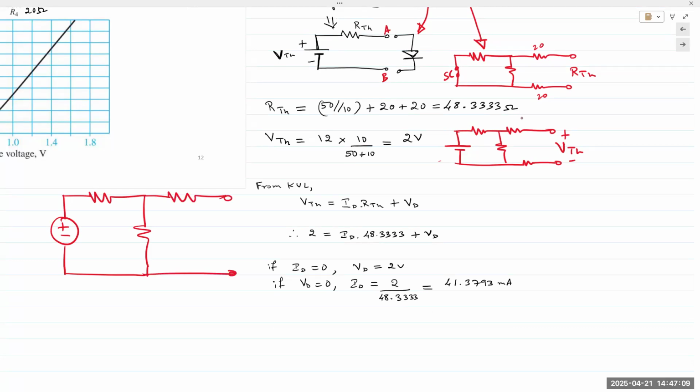If you have a resistor that is connected to a circuit, but the other end of the resistor is open and not connected to anything, what is the voltage drop across that resistor? 0, because current needs a pathway to flow through. If the resistor is open, there is no current flowing through.